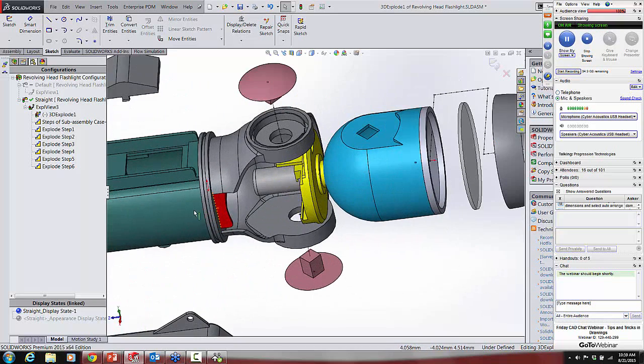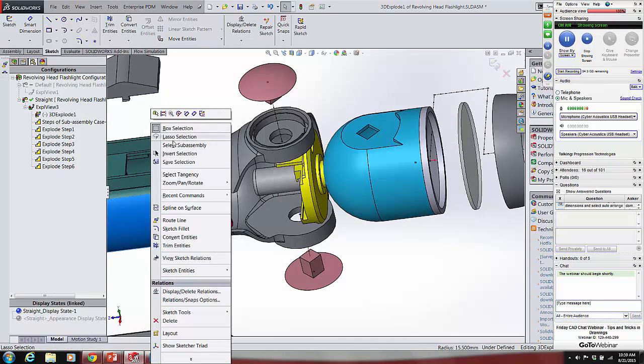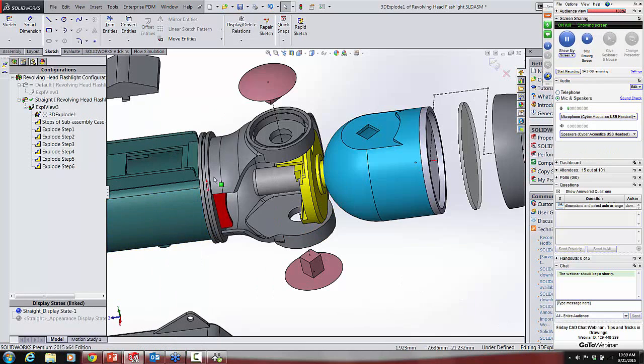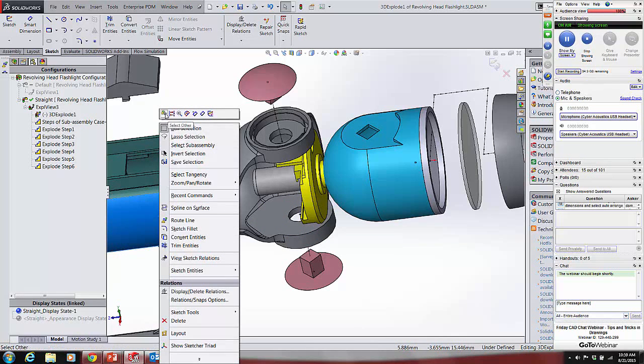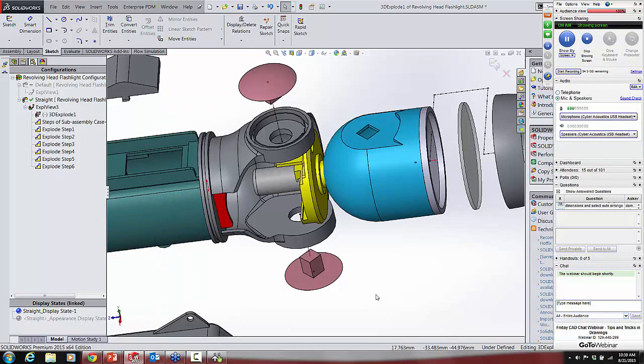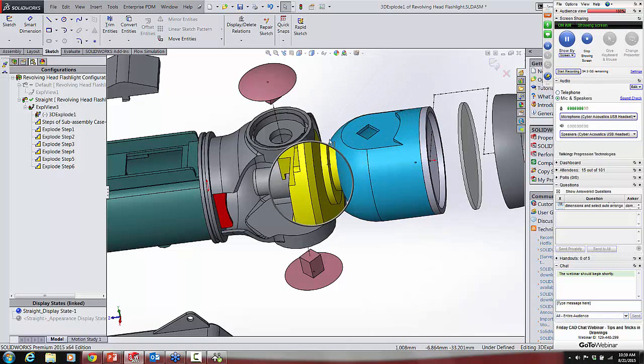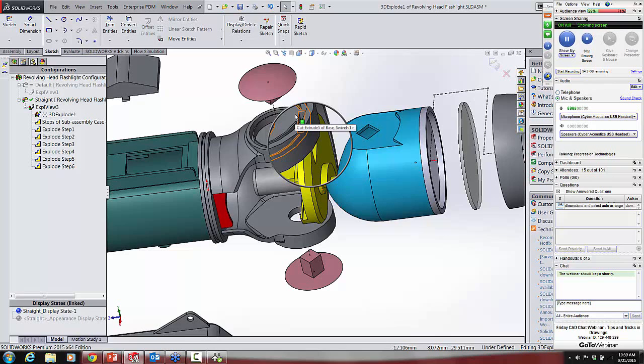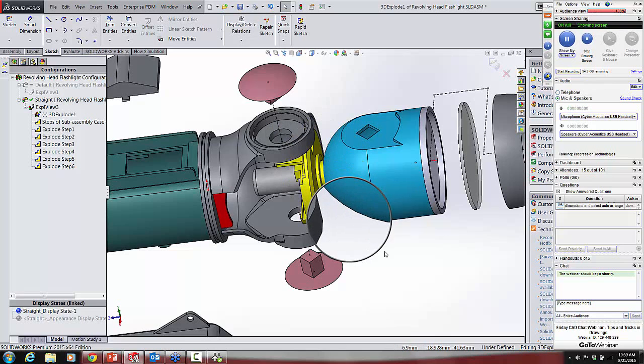And I'm not sure, let me open up this part. The G key is a magnifying glass. That's sometimes beneficial when you're trying to manually dimension a drawing. Hit the G key, it will bring up a magnifying glass, allowing you to select small geometry a lot easier.